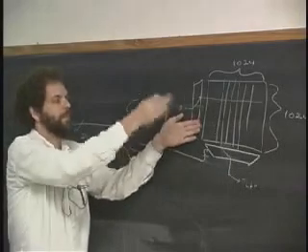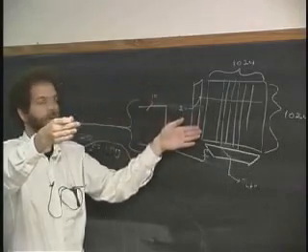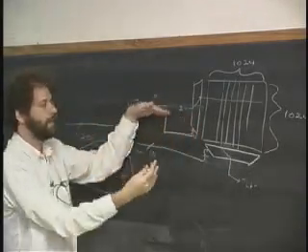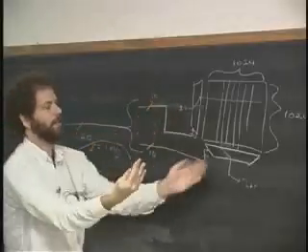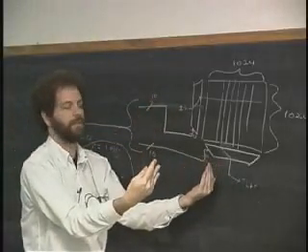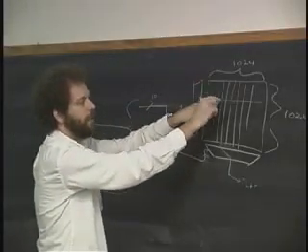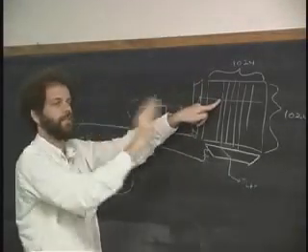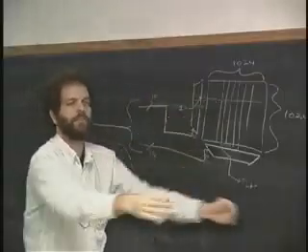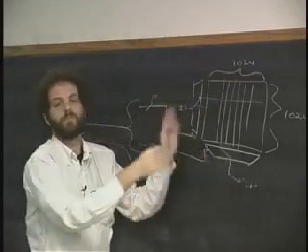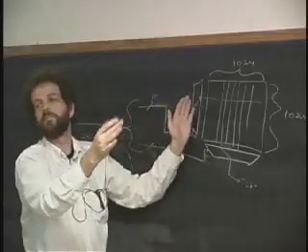And if I take this and replicate it 32 times like so, and have all of them do the same thing, they're all going to go up like this, and they're all going to go across like this in step with each other. Whichever particular place in X and Y I choose here will be the same place along all 32 planes, then I'll get 32 bits out of storage from this 1 mega word system that I have.